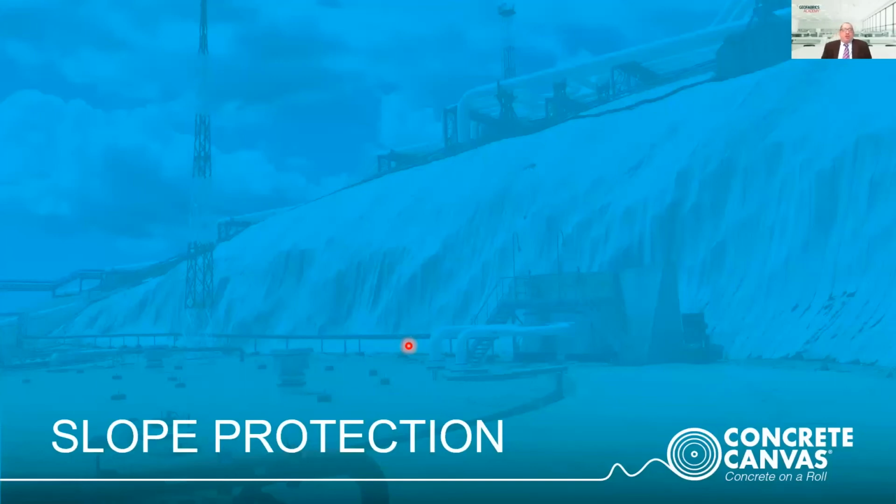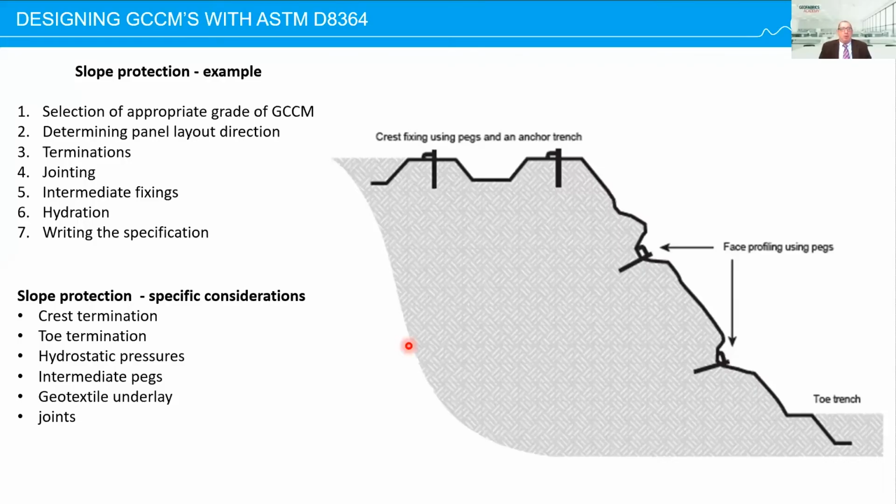Okay, finally, we get into some of the design examples. So a slope protection example. These are basically the same steps that we go through in all GCCM designs. So appropriate grade, panel layout, terminations, jointing, intermediate fixings, hydration, and writing specification. And these are some specific considerations for slope protection: the crest termination, toe termination, hydrostatic pressures, if they're there, intermediate pegs, geotextile underlay, and joints.